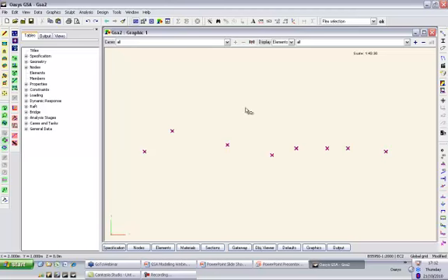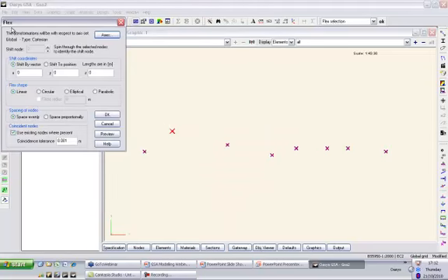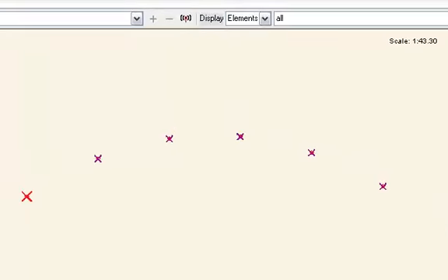Alternatively, if I click on, let's say, that node there, you notice that there is a node in question that the flex command is working on, and then say make those nodes circular. It joins the points up. Or of course, if you want to set a particular radius, let's say of 10 meters, then again you can. This also works for elliptical and parabolic profiles. Can be a very useful trick, this one. The flex command is quite wonderful.